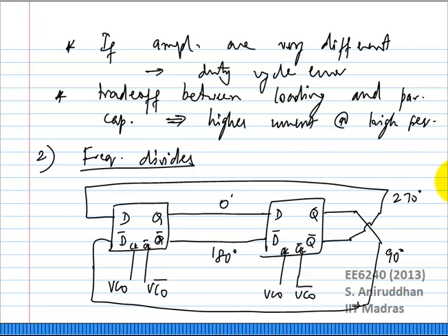So the difference between this one and the polyphase filter is that the VCO frequency there needs to be the same frequency as here, as the output, as the LO frequency. Here it needs to be double. Now the difference is, once you have decided that for pulling you want to go ahead with moving the VCO frequency, then this is a natural winner over the polyphase filter. Okay? Because we said that if the VCO is the same frequency as the transmitter, you are going to have pulling effects. If you want to prevent that, you anyway want to move it away. So 2 or 4x is actually a very good decision to do anyway.